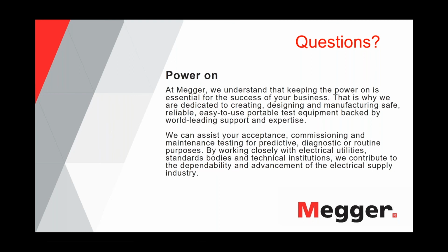Absolutely. Just keep in mind, Javier's right, the sinusoidal test units are typically much lower in test capacitance, in terms of what you can do with it compared to the cosine rectangular. But for the tan delta, you also don't typically go to the maximum output of the machine, because all of these machines, if you look into the data sheets, this 1 microfarad is also at maximum output at 0.1 hertz.